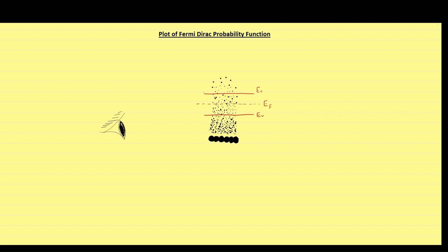As you can see, the density of electrons is maximum in this region, which is nearest to the atoms. This means that the majority of electrons are strongly bound by the electrostatic force of the crystal and cannot be considered as free. Similarly, these are the electrons which are at least trying to make transition to conduction band. Some of them will succeed while some of them will fall back due to insufficient energy absorbed. Talking about Fermi energy level EF, we have already described its significance in the previous lecture, that EF is the energy level where the probability of finding an electron is 1 by 2.